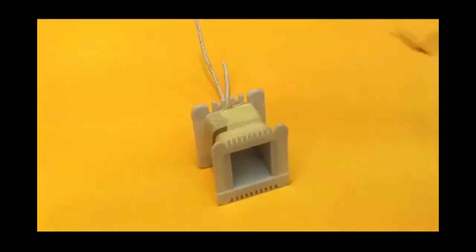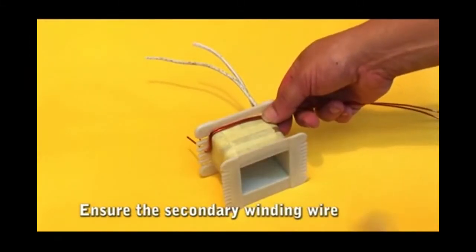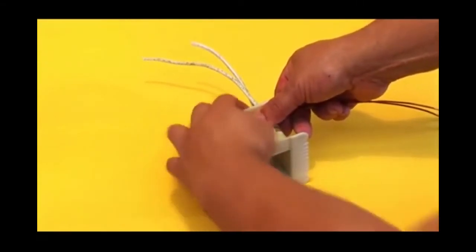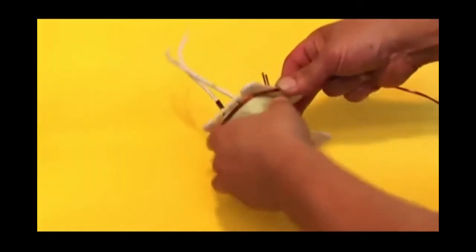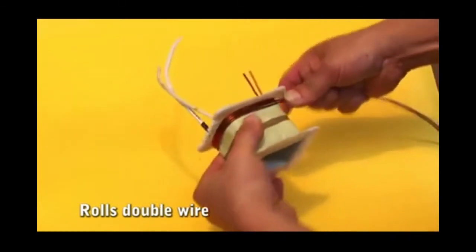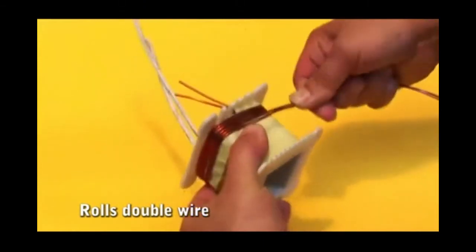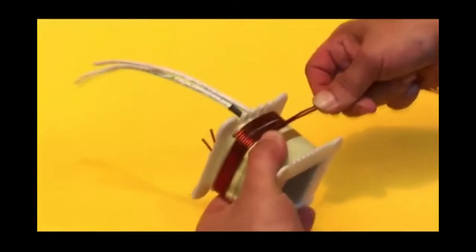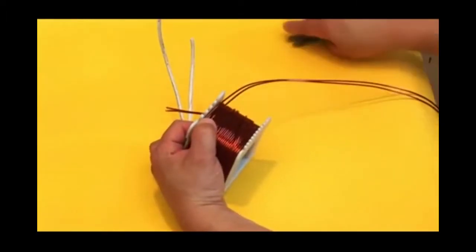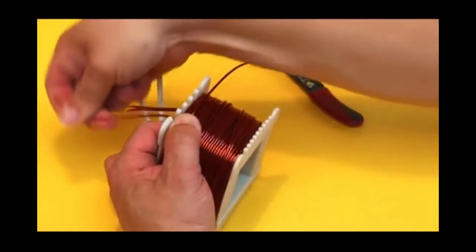Winding the secondary winding. As in this case it is a center tap transformer, the wire is wound twice. Secure with masking tape and wind from left to right, pressing well and taking care not to ride one turn over another, with no spaces between the turns of wire. At the end of winding, cut the wire and insert the tail ends of the wire in the output slots.